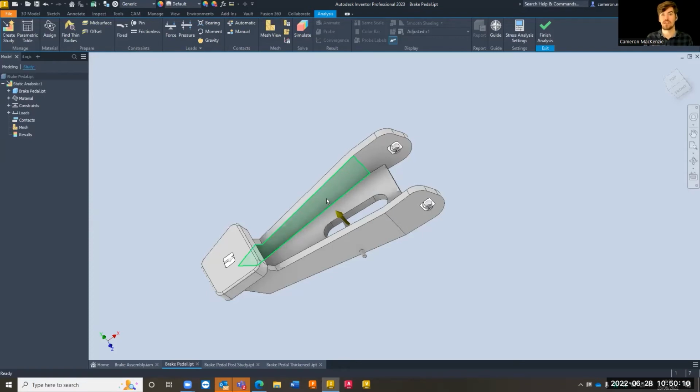And essentially what the mesh will allow us to do is, because we're using a process called FEA, Finite Element Analysis, it's going to break down our component into multiple smaller components, each with their own axes and movement, and essentially allow the force to dissipate throughout those individual faces, if you are familiar with that process.